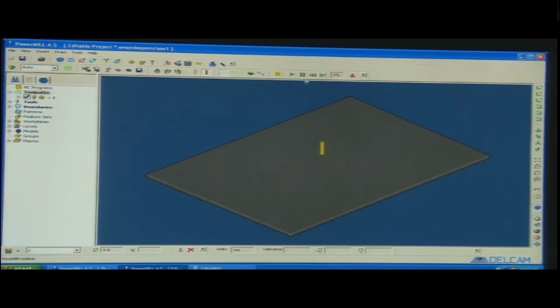It is showing me a sequence, command by command step simulation, each step it will show. Now, I will click on the next step, next step, next step, next. It is command wise, leading in and coming out. Once it has done the machining or some of its operation here, it will come back to the safe height, that is 5 mm.